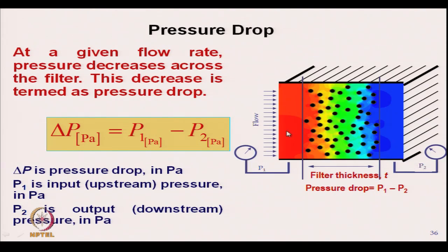This pressure drop is a very important characteristic of any filter medium. Irrespective of whether the filtration efficiency is very high or low, if the filter medium results in very high pressure drop, then the filtration system will actually fail.